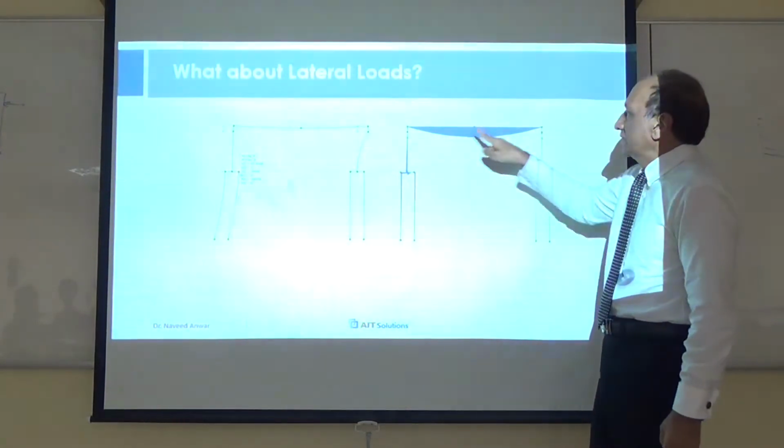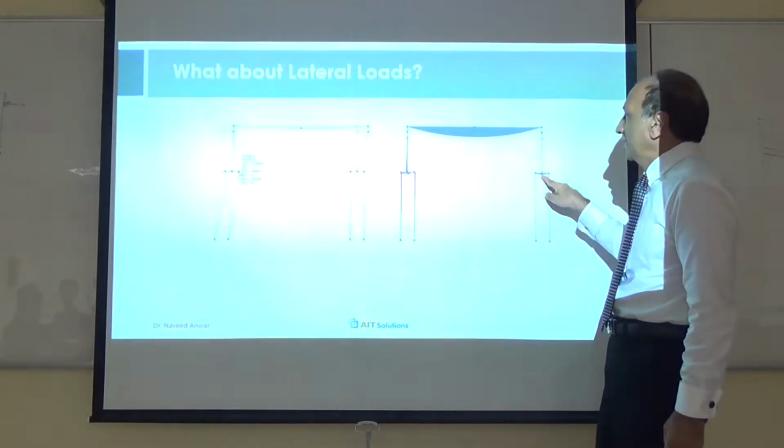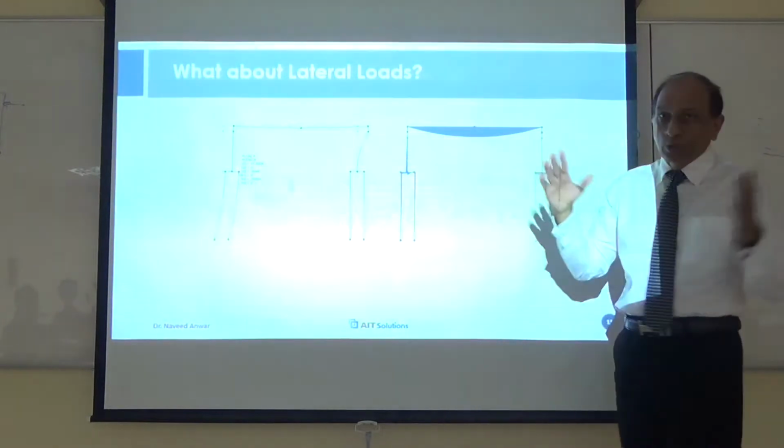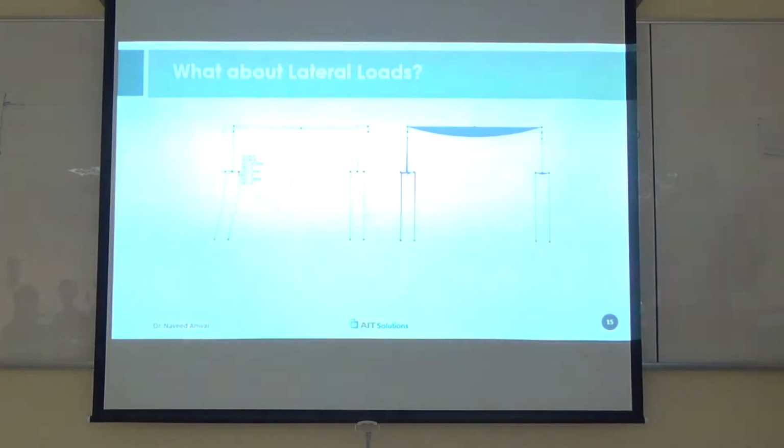If one side is released, one side is not released properly, then your forces will be different, reactions will be different, bending moments will be different. So two sides are not going to be equal, depending upon where the bearing is placed and where you use the pin and where you use the spring condition. But in fact, reality is both are bearings. Both are going to have the same kind of behavior.